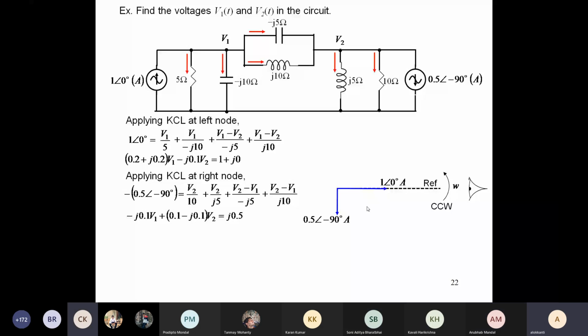The first thing is to write down the equations correctly, because this is AC. We have learned how to represent in the magnitude angle form, which actually helps in the calculation. Then we also have learned how to represent reactances. Instead of the actual circuit elements, you are directly given the reactances because you are not given the value of omega here. If you are given the circuit elements, you need omega. But here omega is not given directly, you are given the reactances so that you can solve it. So ultimately, solving the above equations, you get V1 equal to this type of value, 2.24.